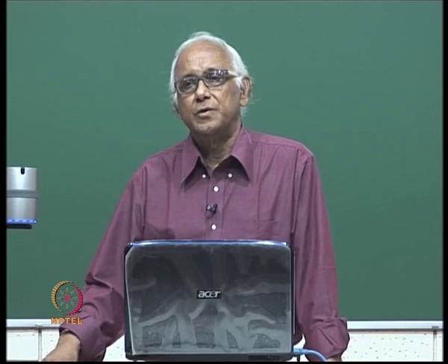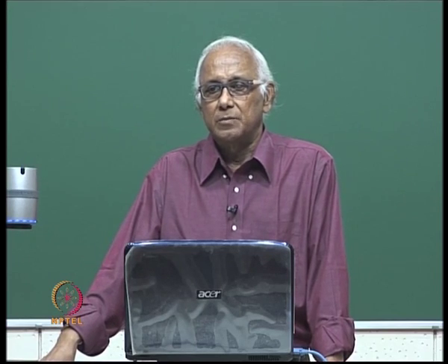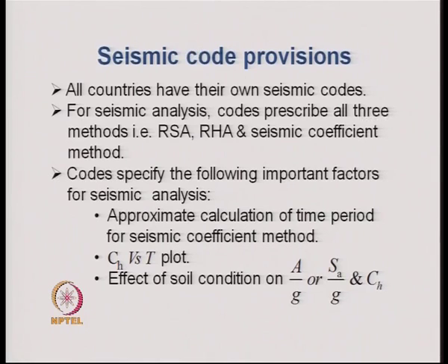In the case of the seismic coefficient method, the entire thing is conceived as a static analysis, and therefore the time period of the structure is obtained with the help of an empirical equation rather than finding it from a dynamic analysis.